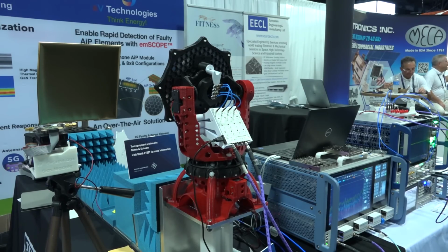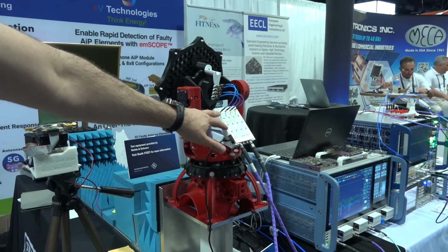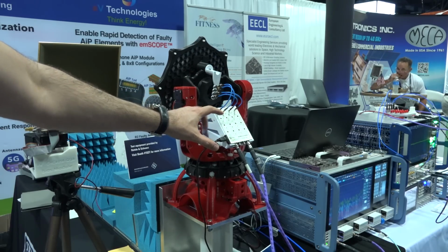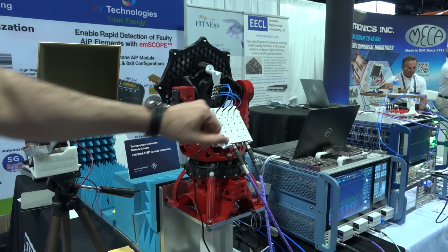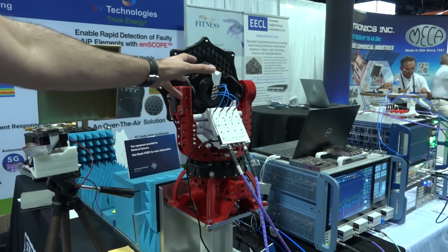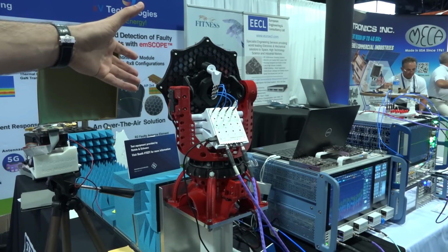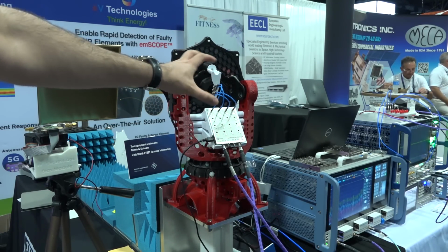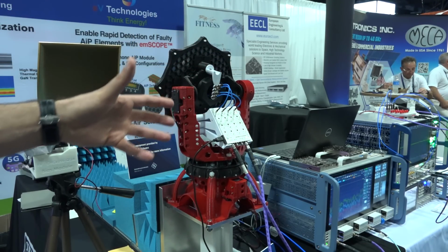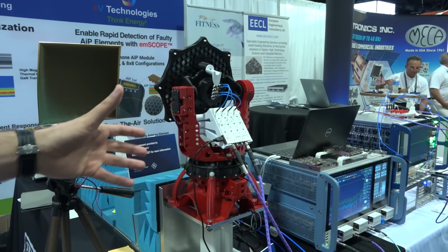So here at EV Technologies, we see a live demo running of a measurement platform that I think is quite interesting. So they do have a switch matrix correlator here that is directly connected to the network analyzer. And there's 100 dB of isolation up to 30 gigahertz between each of these ports. Which means that you can use a multi-port network analyzer and connect it to a very complex antenna structure, and at the same time be able to switch between all different permutations and combinations and make it really 3D, essentially a matrix of measurements across all the different parameters.